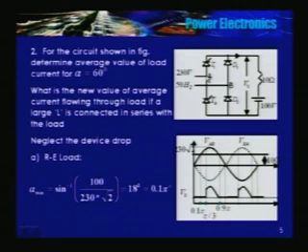So having said that, the thyristor gets forward biased only at 0.1 pi, since sin inverse of 100 divided by 230 into root 2 is 18 degrees, which is 0.1 pi. Beyond 0.1 pi, if you want, you can trigger and the thyristor starts conducting. But in the problem it is mentioned that the thyristor is triggered at 60 degrees. So from 0 to 60 degrees, no current is flowing in the load.